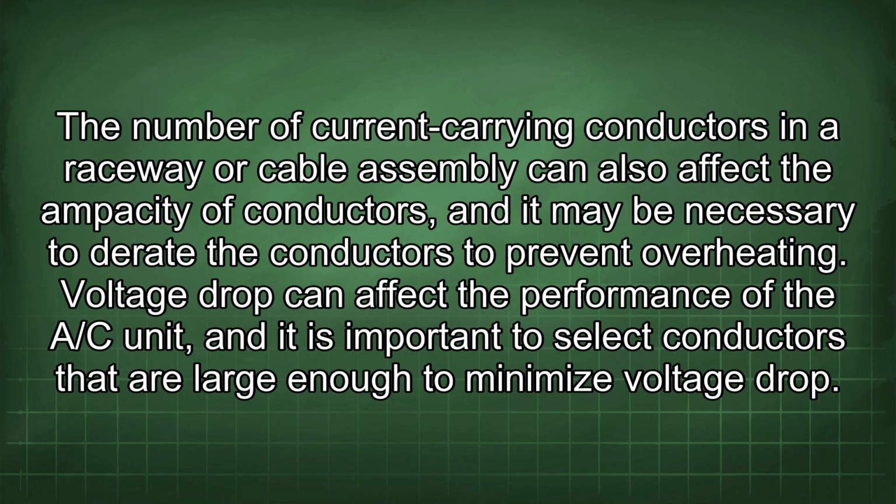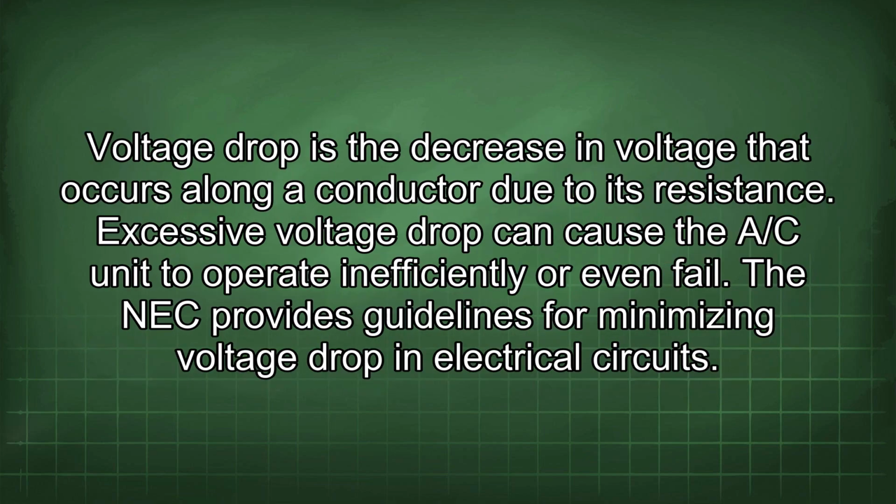Voltage drop can affect the performance of the A/C unit, and it is important to select conductors that are large enough to minimize voltage drop. Voltage drop is the decrease in voltage that occurs along a conductor due to its resistance. Excessive voltage drop can cause the A/C unit to operate inefficiently or even fail.